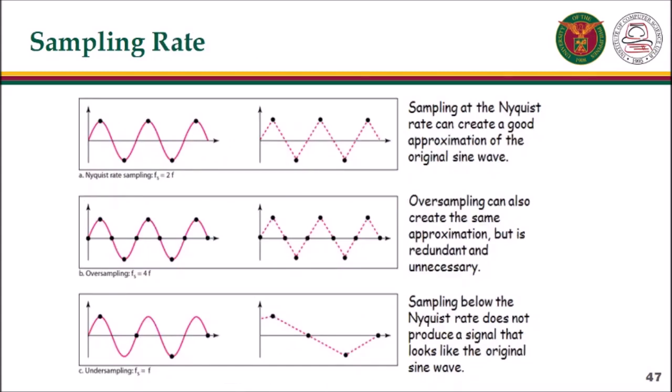One important consideration is the sampling rate or frequency. What are the restrictions? This was answered by Nyquist. According to the Nyquist theorem, to reproduce the original analog signal, one necessary condition is that the sampling rate be at least twice the highest frequency in the original signal.